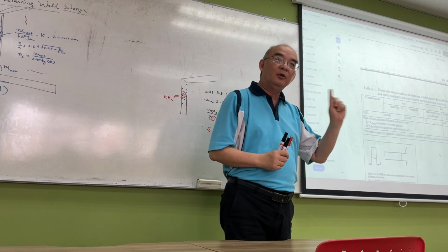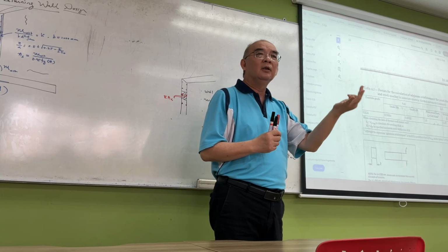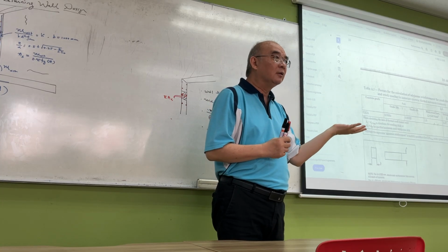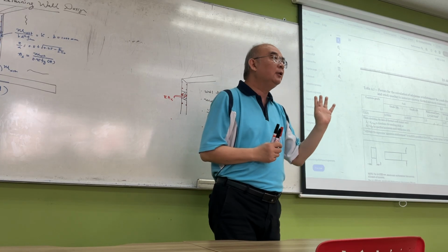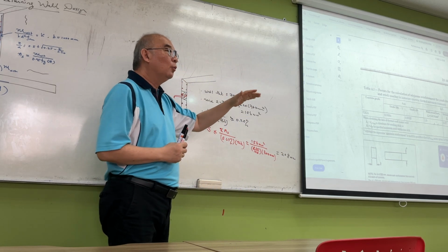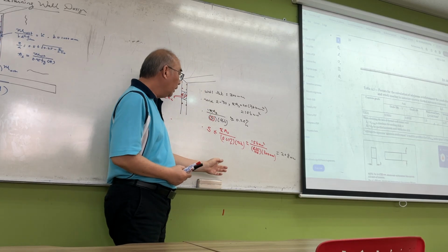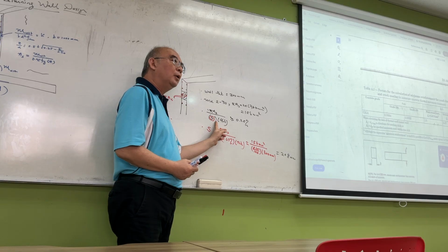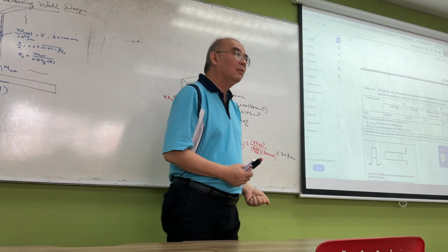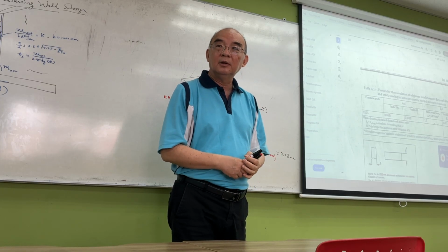And I say, okay, I'm going to use T10. You can use T10, T12, T8, T16 or whatever. Right? So you have to fix that one first. Then you choose the spacing. Then based on T10, what's the spacing? Okay? Or you can reverse. You can say, okay, I want to use a spacing of, let's say, 150. What bar size should I use? Should it be T8? Should it be T whatever?